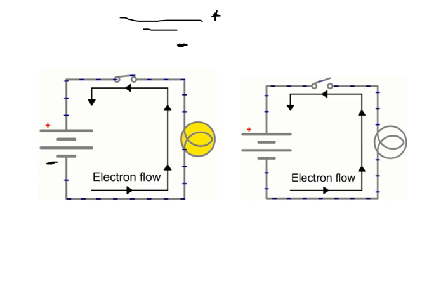So just to recap one more time, if I were to ask you to tell me which one the hot wire is, I'll label two of them. This is wire 1 and this is wire 2. The hot wire is number 2, because it's the one that is receiving the source of electrons. It's going to the load, and then the neutral wire is going back to start.